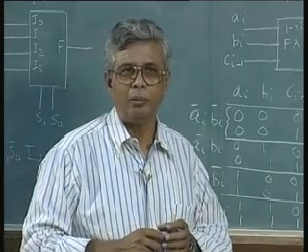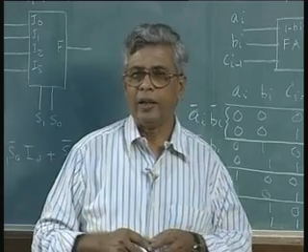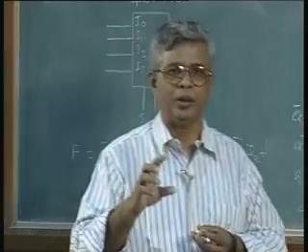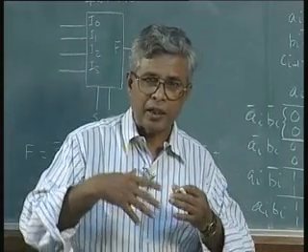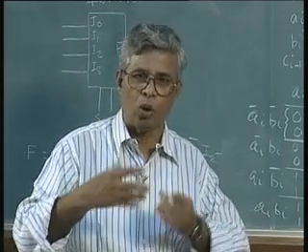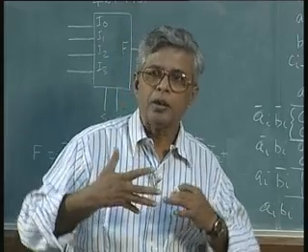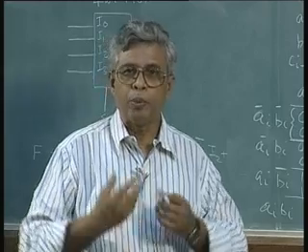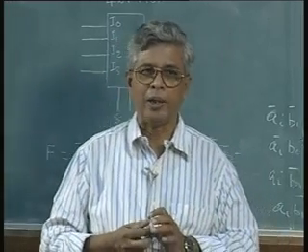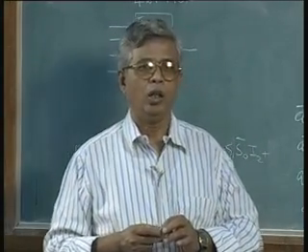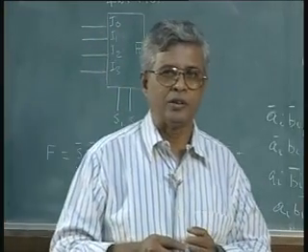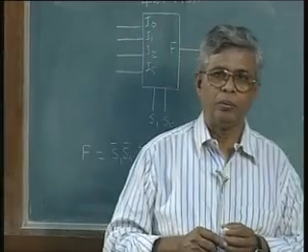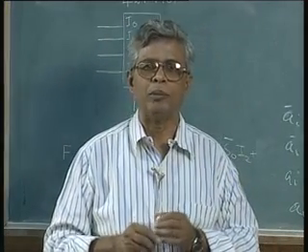As an example, multiplexer I took as an example, full adder I took as an example, so that the concept is clearly understood and it is also simple. Think of this as a bigger and bigger problem. As the problem grows, we can get more and more complex circuits using multiplexers. It can be proved, just as we have proved in our earlier combinational logic course with gates, that all logic functions can be implemented using AND, OR, inverters to start with, and further can be simplified to NAND gates and OR gates. It can be proved that all the combinational logic can be derived using multiplexers.